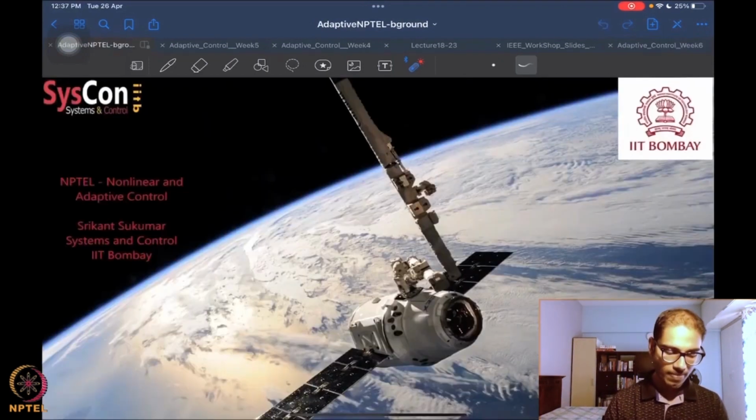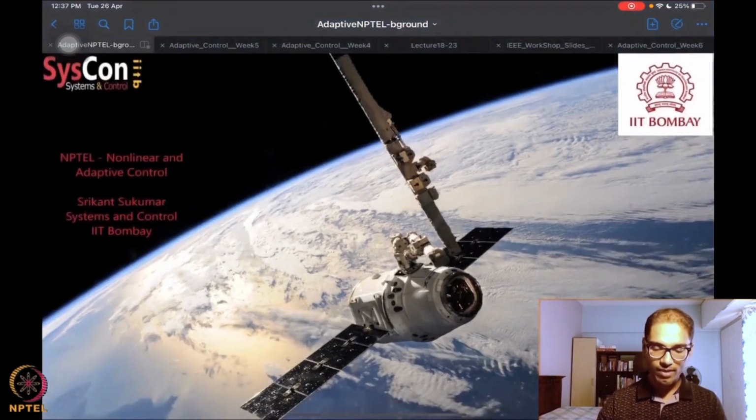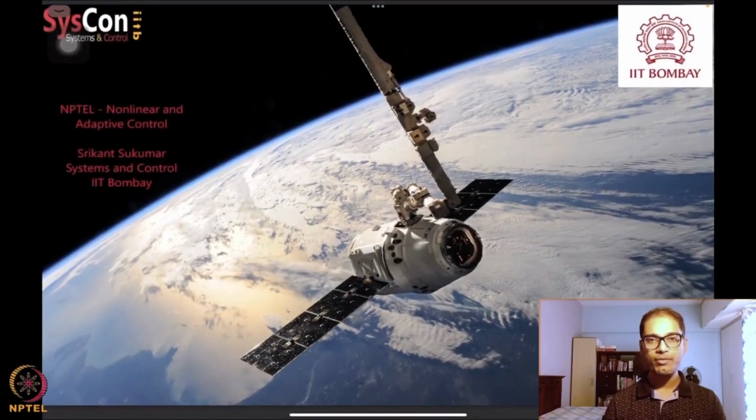So what we saw today is the adaptive control for a second order system. And by the end of the session today, we could only arrive at the detectability obstacle. The detectability obstacle is that because of a choice of a non-strict Lyapunov function for the original known parameter case, we could not prove that the position state converges to zero, so that it converges to the desired trajectory.